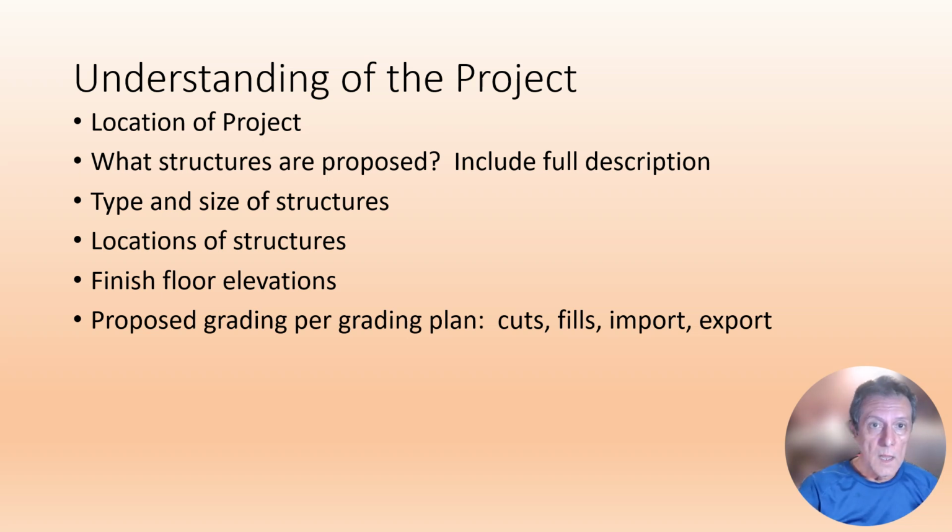When you're doing the proposal and investigation, having a grading plan is very, very important and very useful. Sometimes you don't have that grading plan, but the grading plan will show you where the cuts are going to be, where the fills are going to be. Are you going to need to import suitable soils, or is it going to be a balanced site? In other words, the amount of cut soil balances out the amount of fill soil that's going to be placed to build up certain areas of topography.